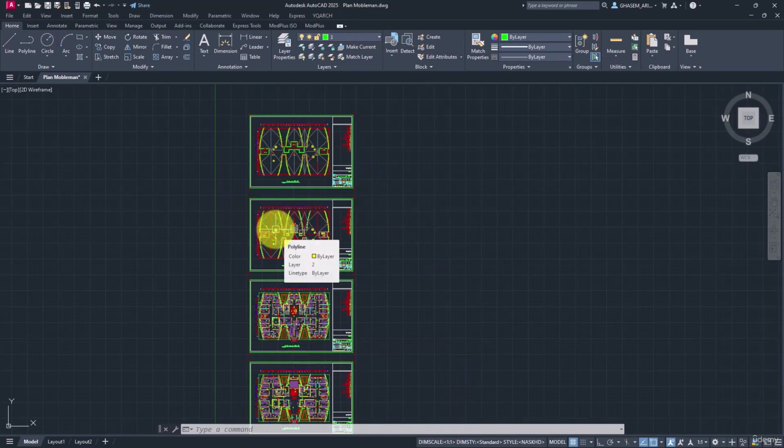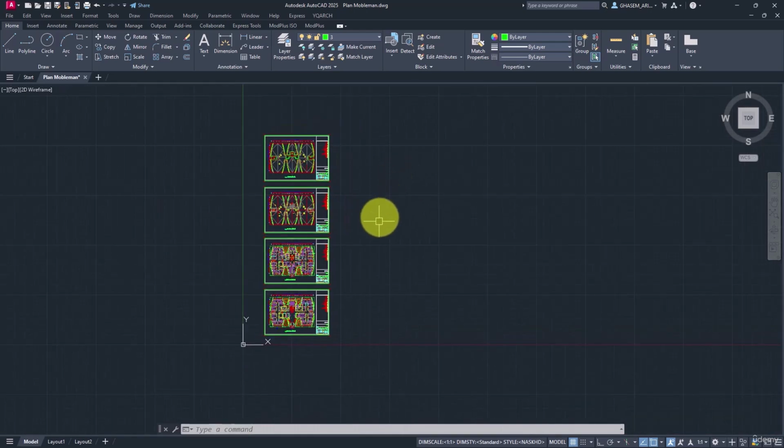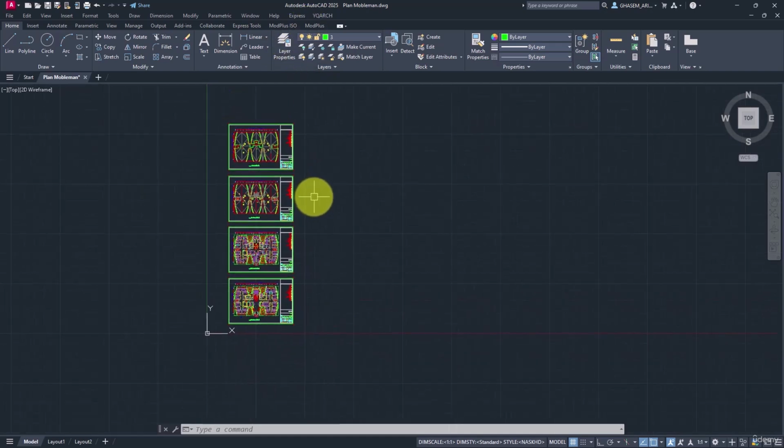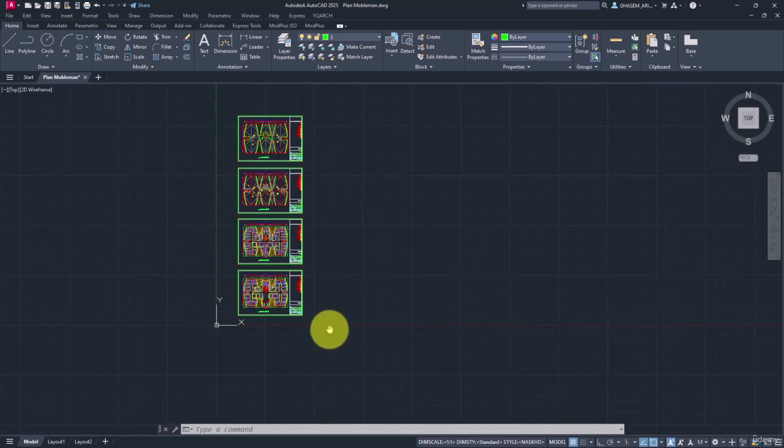Here we have a CAD file, as you can see, and if we want to consider it as a reference view in our Revit project, you may have too many plan views, filled regions, and descriptions, so you'd better not import the entire CAD file into Revit. Since it is difficult to manage, it increases the file size, and also DWG files that contain more than 10,000 objects cannot be imported to Revit. So the count of the objects must be less than 10,000.